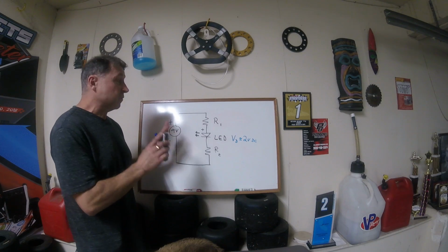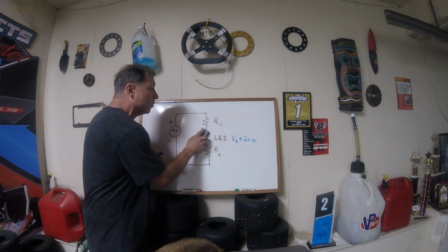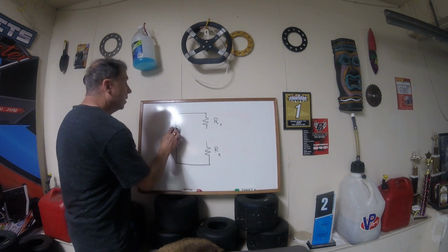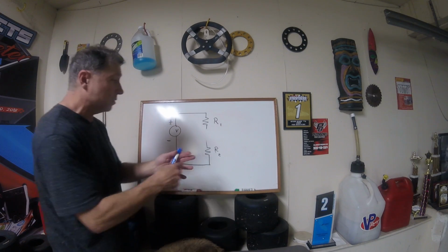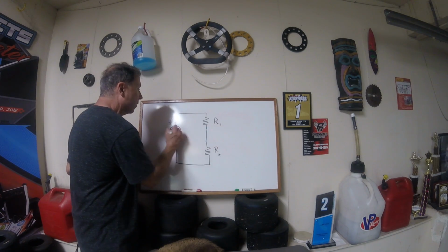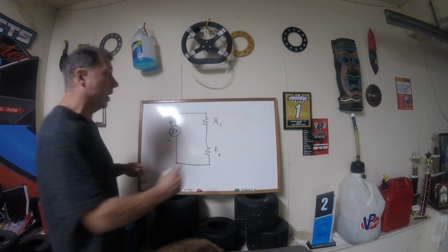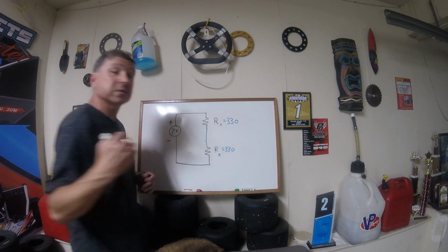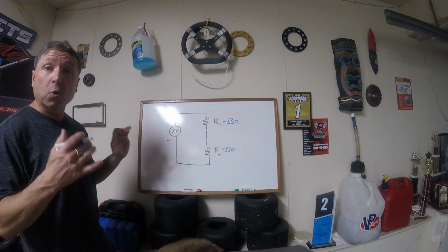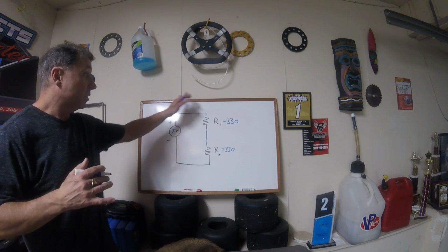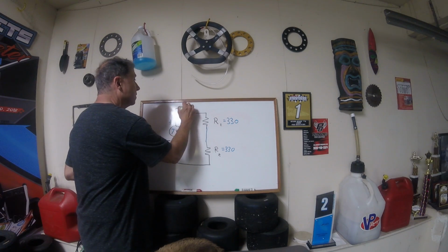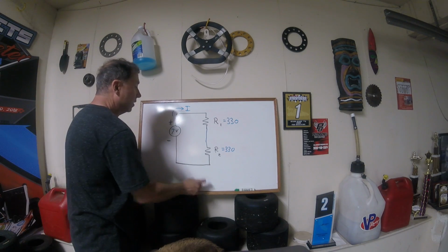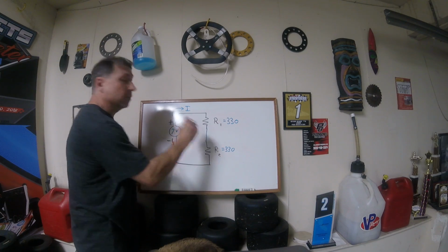So for our purposes for the analysis, I'm going to temporarily take the diode away. Remember, that was a constant 2-volt drop. And I'm going to say across the 2 resistors, R1 and R2, connected together, we have a 7-volt supply. R1 was 330 ohms, R2 was 330 ohms, like so. 7-volt supply. So we use Ohm's law to calculate the current flow. Conventional current flows this way, like so, I for amperes. And electron flow flows from negative to positive, the other direction.